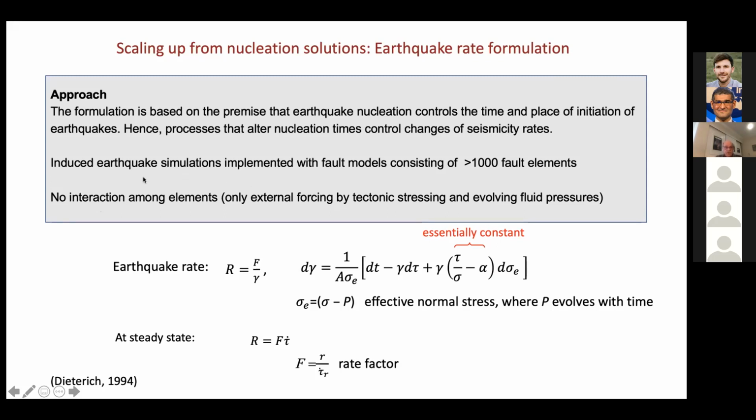And for induced earthquake simulations, we've implemented fault models, and I'll show you some with more than 1,000 elements on the fault. So we can see how earthquake rates vary along a fault based on how stresses vary on the fault. And a limitation of this model is that there's no interaction among fault elements. So it's only the external forcing that drives the earthquake rates.